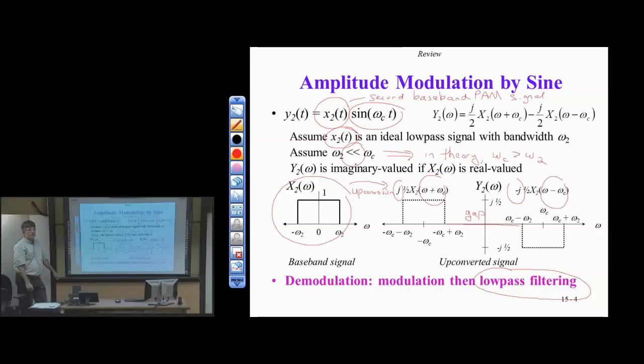Go ahead. Does having 2 filters... No, they're FIR. These will be FIR. Now you're right, this filter here doesn't have to be. This could be either IIR or FIR. That is correct. But for the pulse shaping for the match filter, we know it's finite impulse response, simply because our pulse shapes are finite in duration. But again, for simplicity, we can just replace it with the match filter.